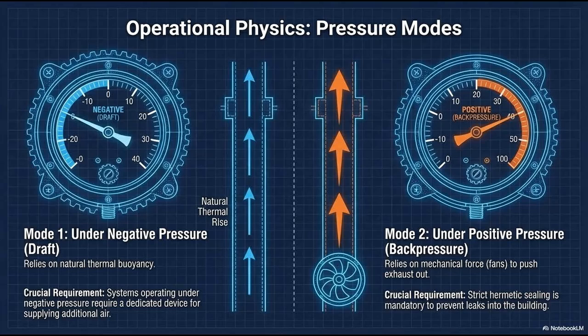The winner of the showdown. Yes, because thin metal has very little thermal mass, and it's surrounded by insulation. The hot exhaust flashes the metal past the dew point in just 1 or 2 minutes. So it achieves a safe, dry regime almost instantly. Not to mention the metal is completely impermeable, so it doesn't absorb the acid even when it does condense.